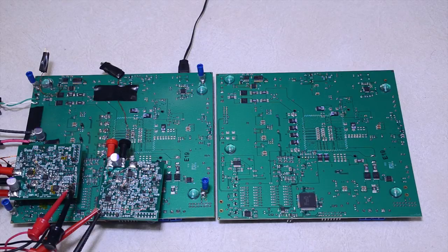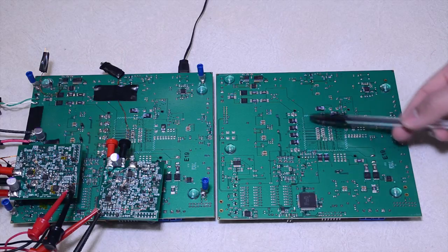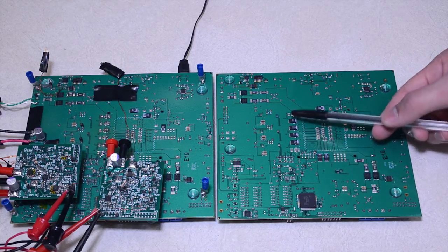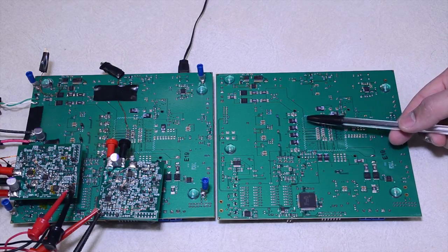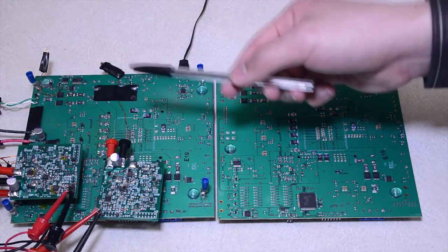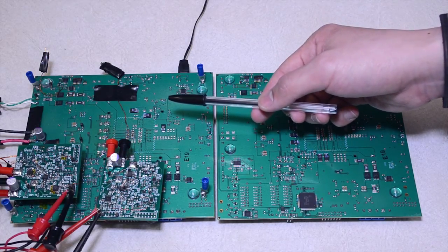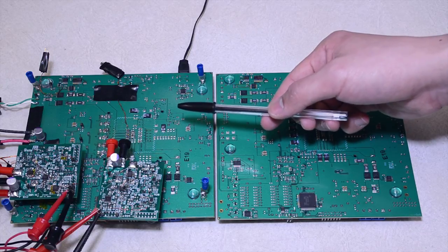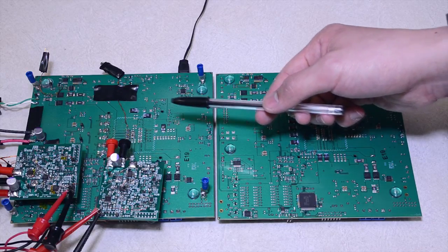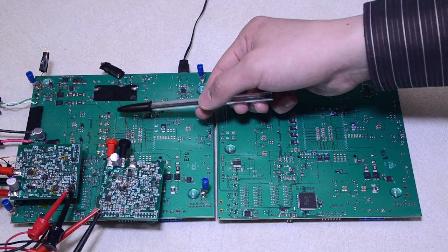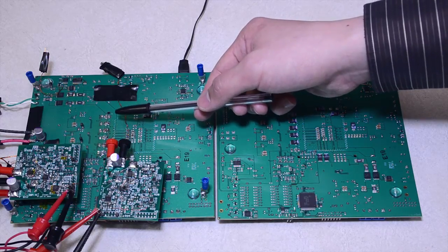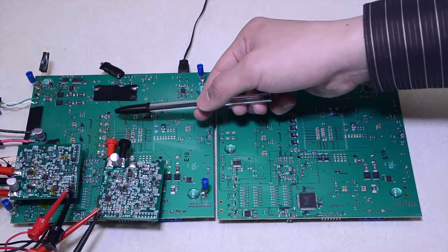To demonstrate the benefit, let's compare with the motherboard on the right-hand side with a low bandwidth design around tens of kilohertz. We can see multiple bulky output SP caps are needed to meet the AVP requirement. Then, after applying our interleaving method with high bandwidth design, as shown on the motherboard on the left-hand side, the bulk caps have been removed and replaced by some decoupling caps outside of the socket.